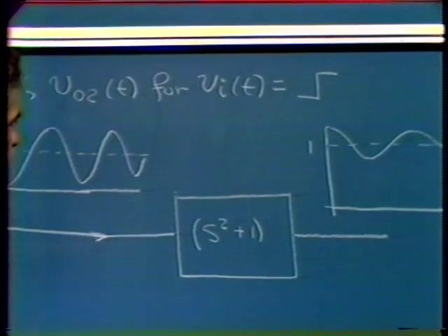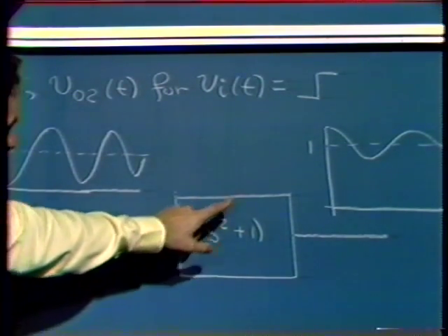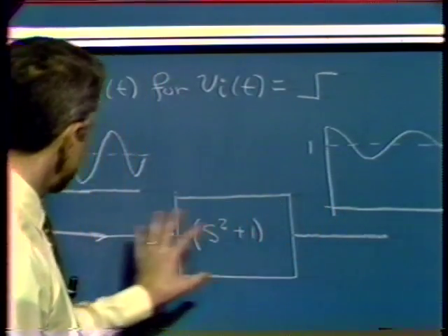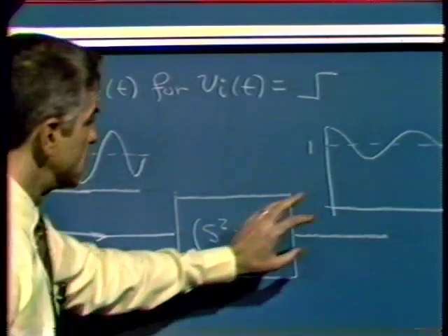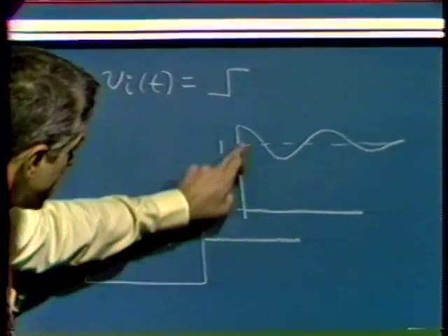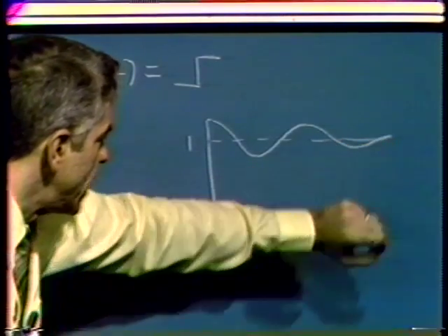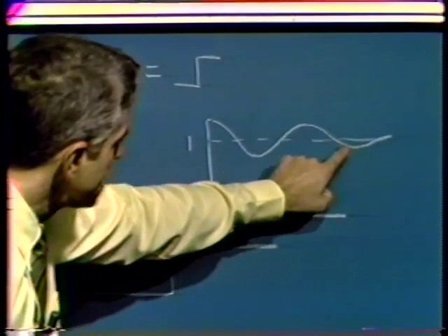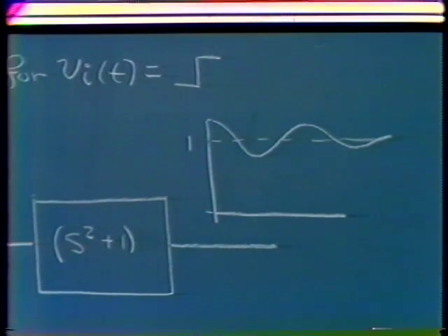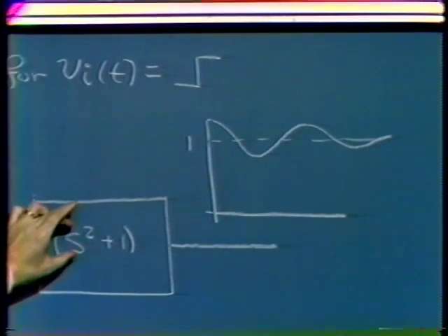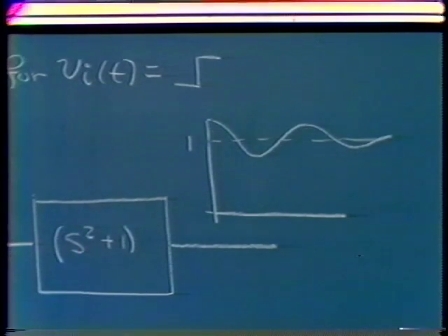Well, we can also argue that the initial value and the final value of the step has to be equal to 1 if we had a unit step. That's a fairly simple application of the initial value theorem and the final value theorem. And by putting those things together, we conclude that the step response of the overall system, the poles plus the zeros, is unity or very close to unity initially. It's unity at high frequencies. And what we get is just a little bit of residual of this sinusoid that's quite well filtered out by the complex conjugate pair of zeros.